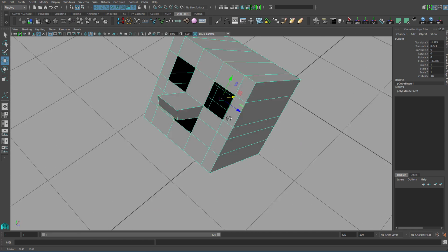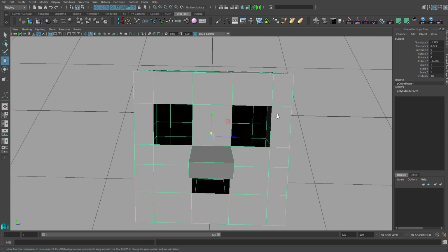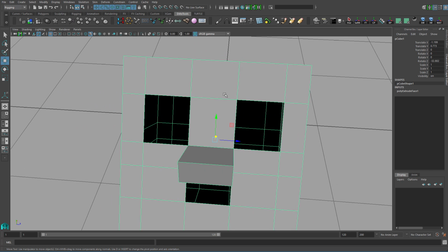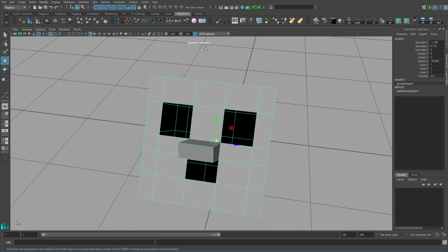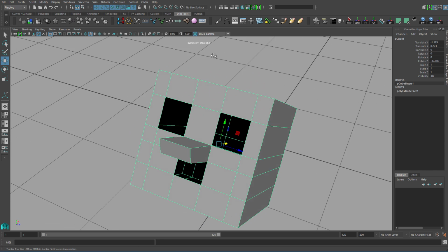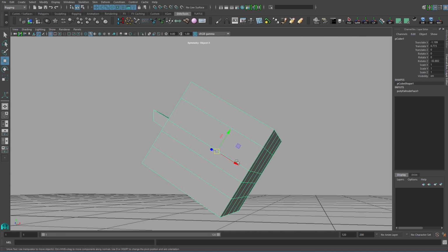Now let's talk about symmetrical editing. If you're holding down the W button again and holding down the left mouse button, there is symmetry on the top. Let's change the symmetry to toggle it on. When symmetry is on, Maya gives you a heads up on which direction the symmetry will be mirrored. In this case, it's object X. Now this object X is this direction.